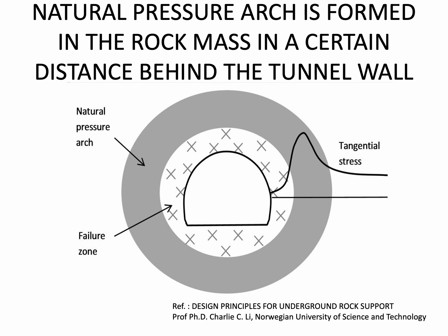and become almost constant. In this zone where the tangential stresses increase to their maximum, a natural pressure arch is created which supports all the rock loads from above and sides that are coming on this failure zone.